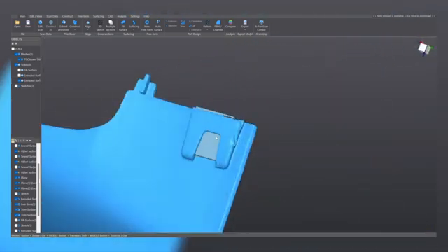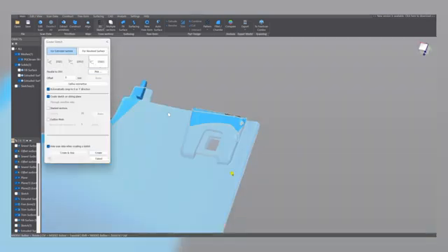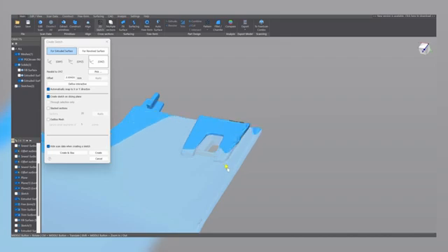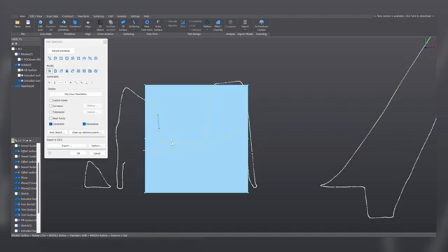And now let's focus on this cutting over here. For this, again, we repeat the process. We select the proper plane and we move the slicing plane accordingly. Great. Again, Create Sketch on Slicing Plane is selected. And we best fit these three lines here. We join them. We fillet them. And let's extend these lines beyond this body and close the sketch.